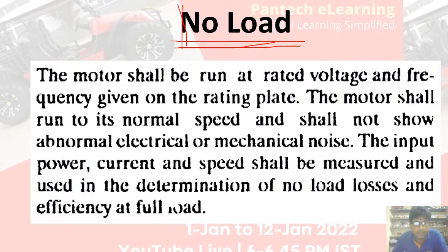No load test, as I was telling, the motor shaft will be decoupled. The machine will be allowed to rotate without any load. The motor shall be run at rated voltage and frequency given on the rating plate.